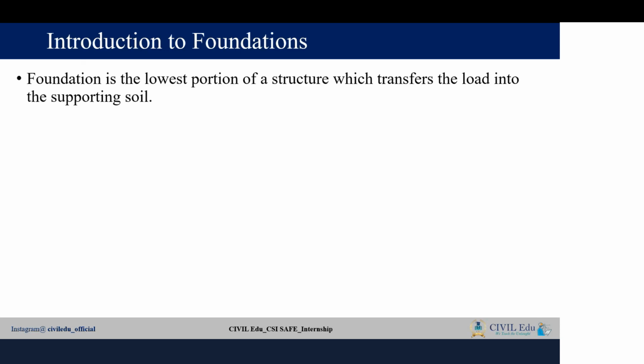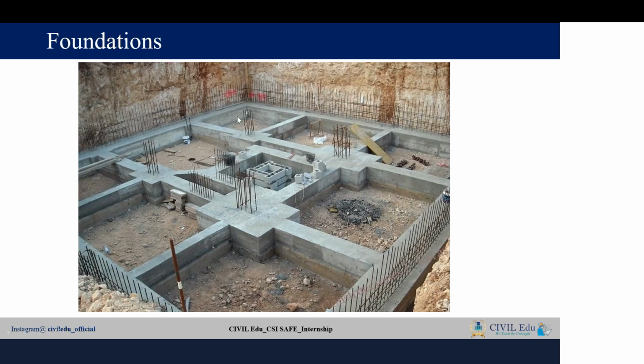Foundation can be defined as the lowest portion of a structure which transfers the load into the supporting soil. Suppose you observe this particular figure, here there is a foundation and there is soil. What is the purpose of constructing the foundation? The purpose is not to carry the load. We are not designing the foundations or footings to carry the load. The purpose of constructing the foundations or footings is to distribute the load to the soil.